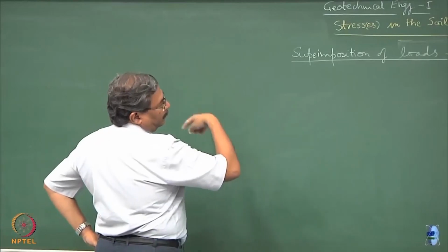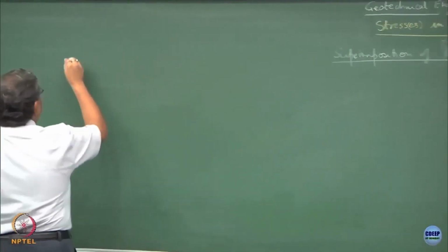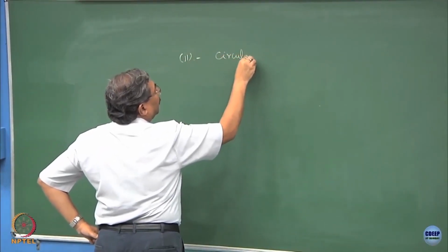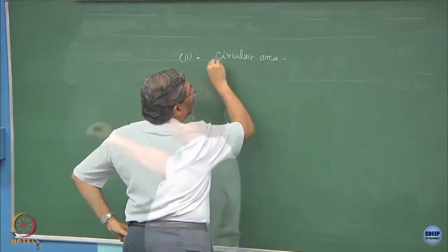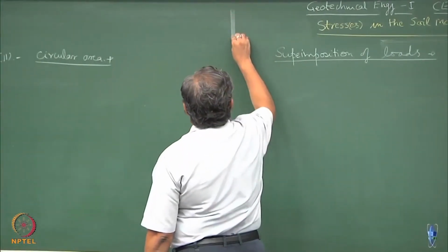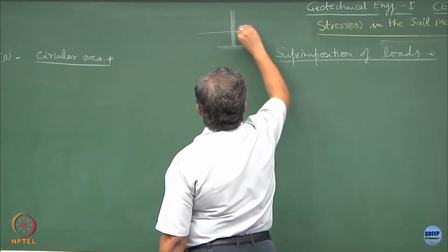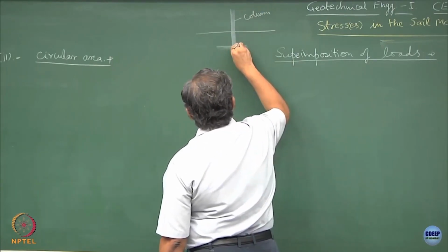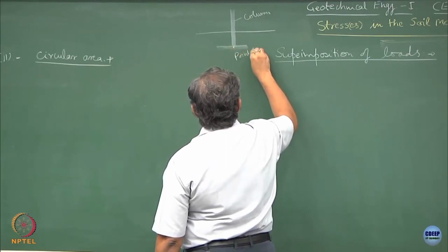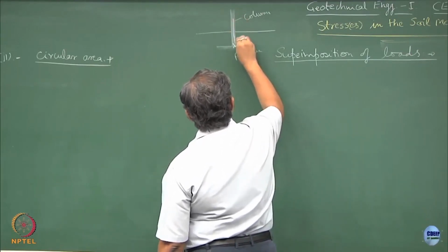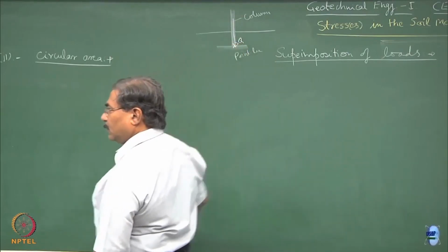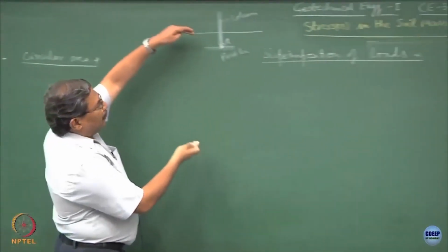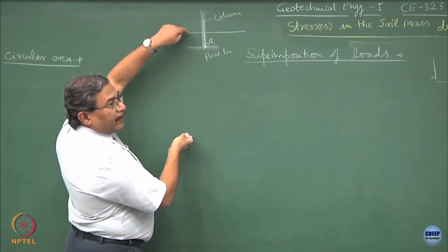Suppose I ask you to find out, in the second situation, from point load we will move on to the uniformly distributed circular area. Until now we have talked about a foundation system where this is the column. So, this is the point load. The best possible approximation would be that the Q is acting at a given point, though the foundation is also of finite size, but this is an approximation as compared to the domain of semi infinite soil mass. Clear?